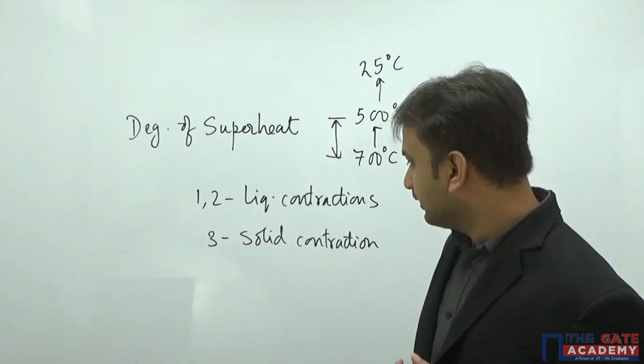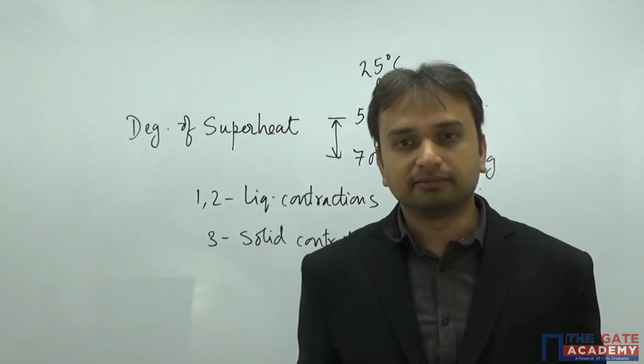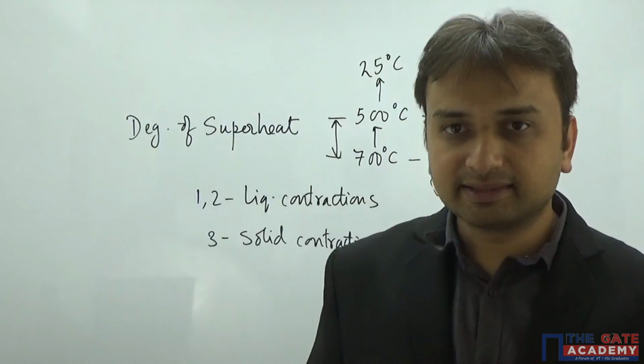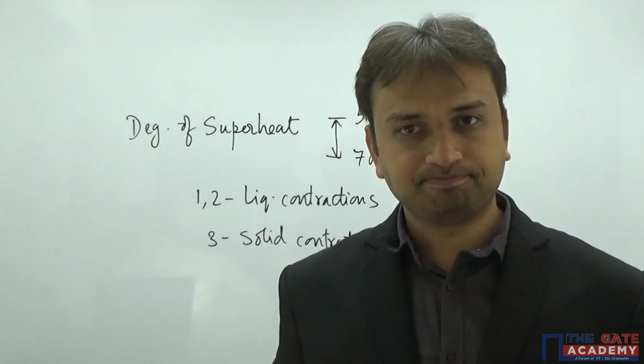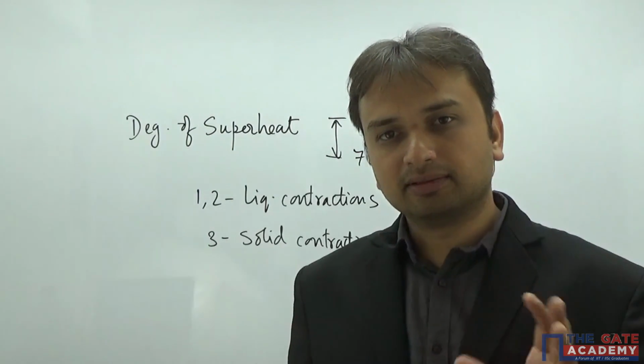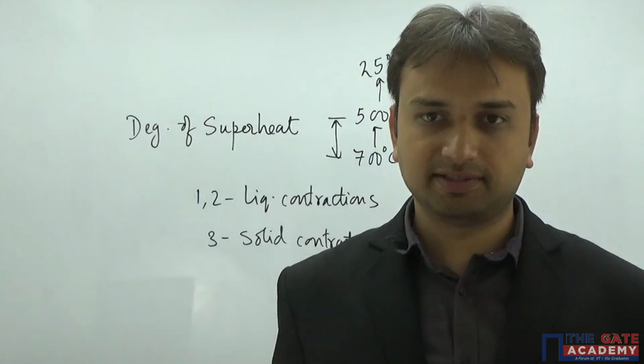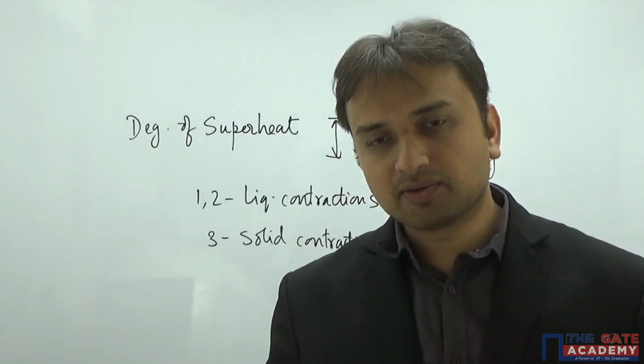It's beautiful. And then solid contraction. This solid contraction is because now the riser can supply only the molten metal, right? But in the third stage, in solid contraction, there is no liquid metal's role, right? So what we can do, we can provide the allowances here, right? So we provide the allowances in the pattern.